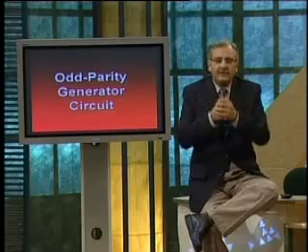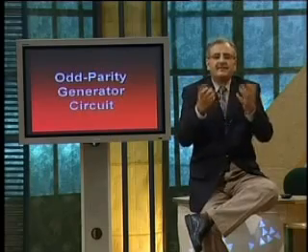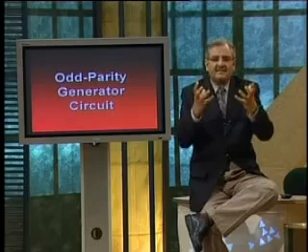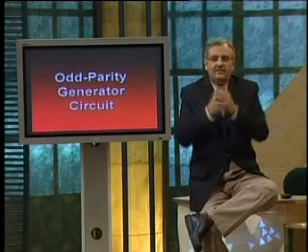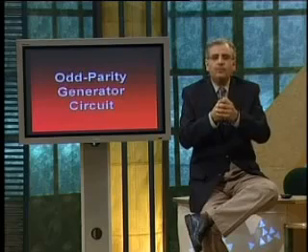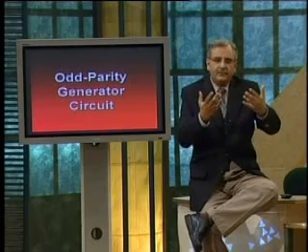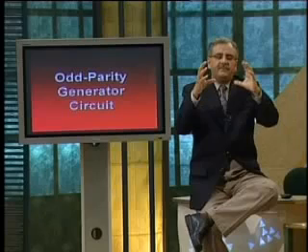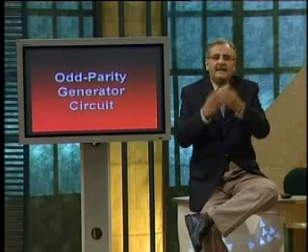Now how will we build the odd bit parity generator circuit? Well, let us just discuss that. Basically we have to make a function table and a function diagram, which would indicate the input and output, with the standard assumption. Let us look at the function diagram of the odd parity generator circuit. Now let us use 4-bit data. The function table has 16 different inputs. That means the 4 bit data has 16 different combinations. Now, what is the output?